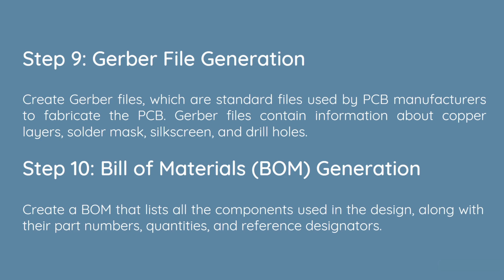Step 10. Bill of materials, BOM generation. Create a BOM that lists all the components used in the design, along with their part numbers, quantities, and reference designators.